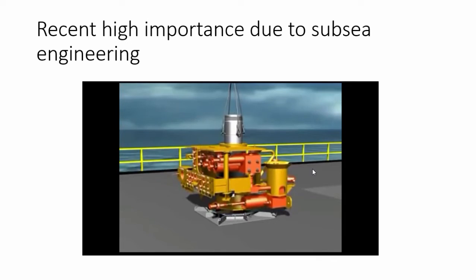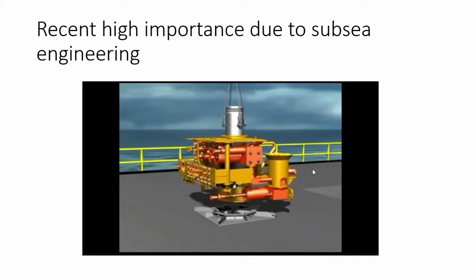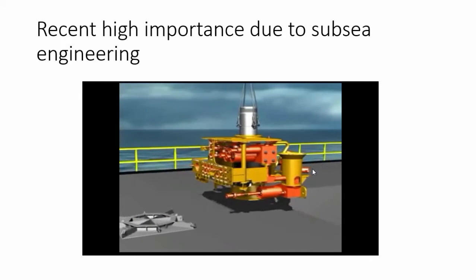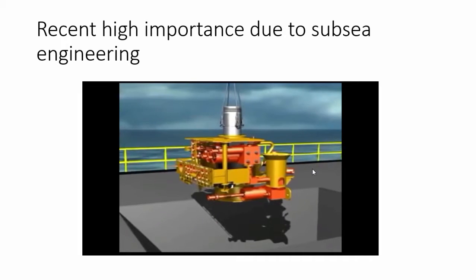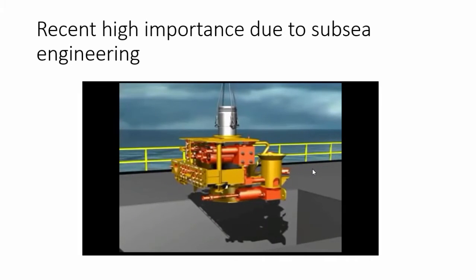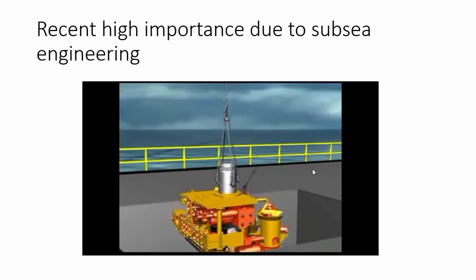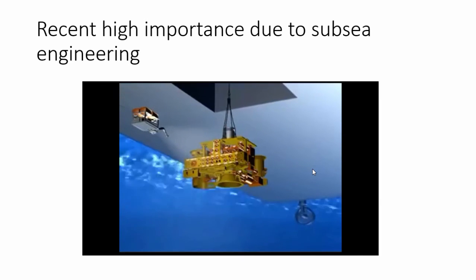Right, there it goes. So you can see that there are 4 cables, not 3 as we usually do, because of the symmetry that is involved. First thing, notice that this is not lowered over the side, but through the center of the barge. Part of the reason is that it's small enough for you to do that. And the second thing is it's so heavy that if you put it on the side of the barge, you will get lots of torques and moments that you want to avoid. So you want to keep this close to the center of mass.